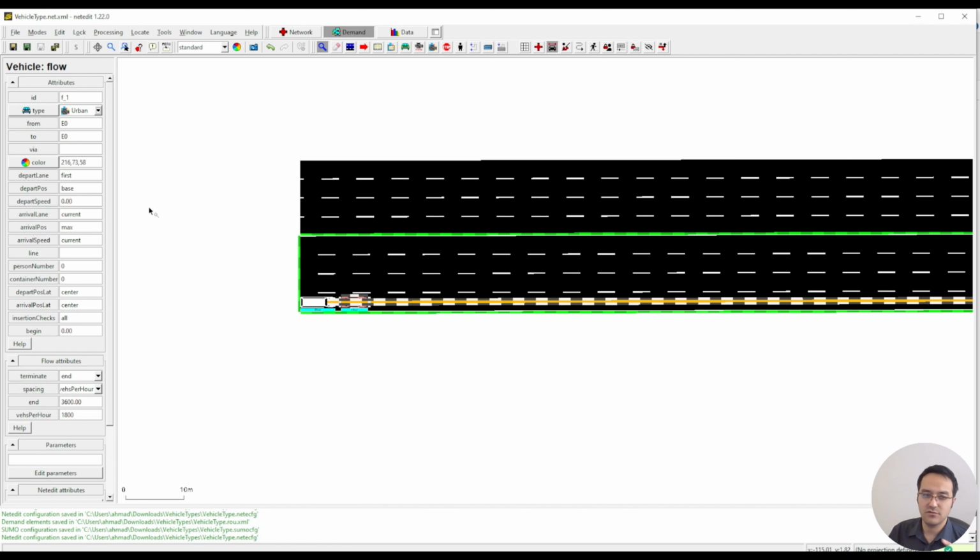So you see how you need to play around sometimes in SUMO. That's how engineers do the work. It's not necessarily very straightforward. So you got how to change the vehicle types: you need to create something like a vehicle, then select it, then change it from here.